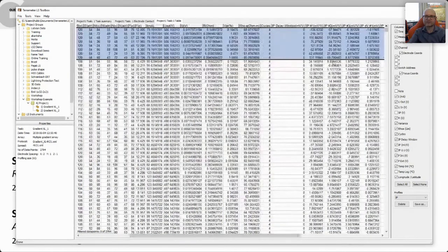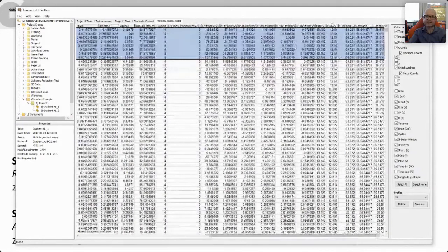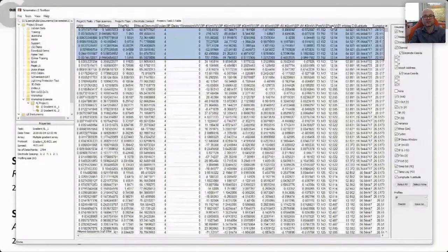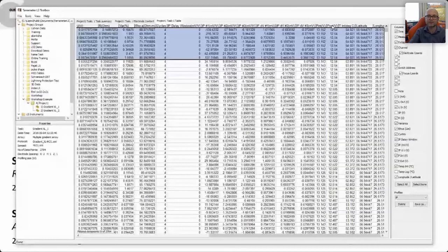Towards the end, we've got information on the IP windows as well. And right at the end, we can see what the external battery voltage was. You can see this one was at almost 12.6. That's a good quality, healthy, fully charged lead acid battery. I'm happy with that, so I wouldn't expect any of my problems to be coming from the power source.